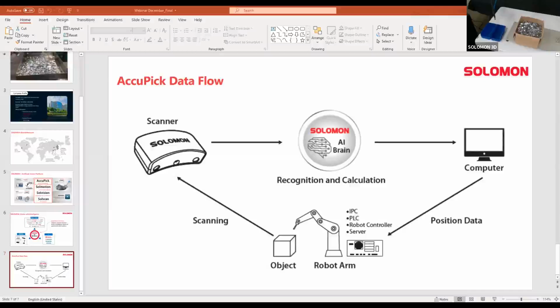I have a bin config block, which I'm going to use to set up a bin virtually in my 3D point cloud so that when I recognize the objects, I know where they are in reference to my bin wall, so I don't cause a collision. This filters block here is so that I ensure that I only pick the best objects first. It's quite important because these parts are quite small and quite shiny. So sometimes the point cloud does not produce a good enough pick point. So we just have to make sure that we pick the best items first.